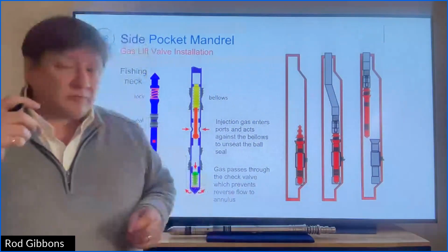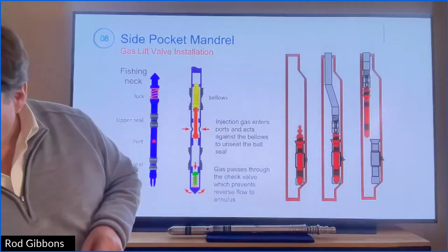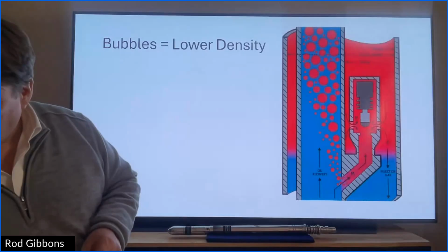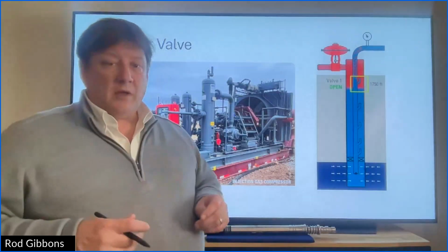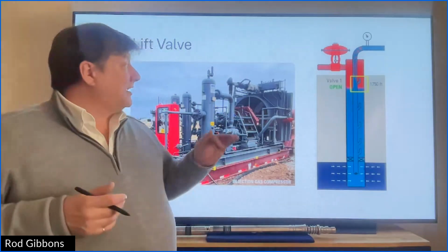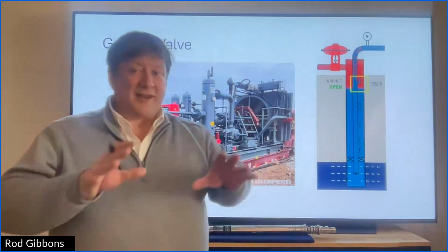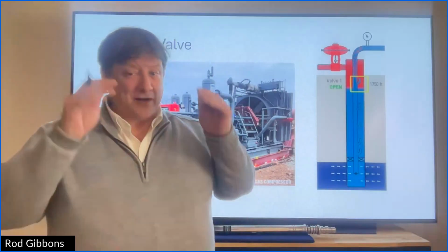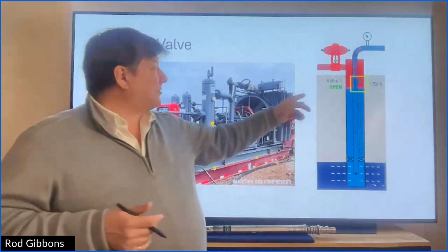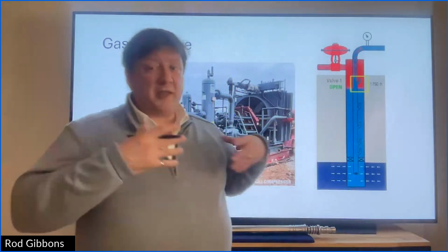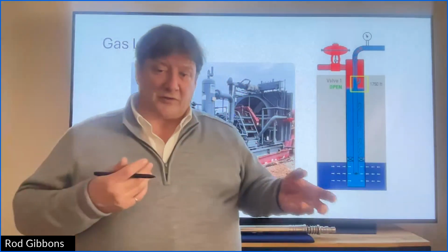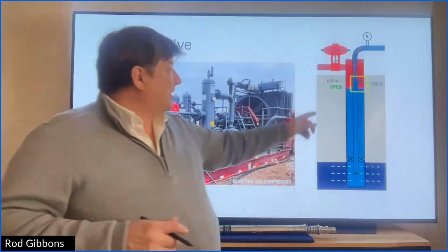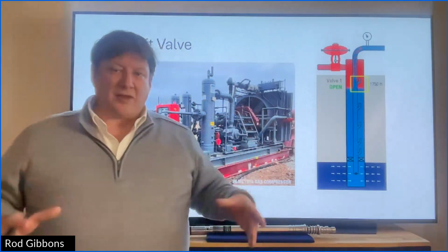So there's a question here. Is the gas in the annulus for the gas lift system pumped through a control line, or is it pumped directly into the annulus? That's a good question. I'll just go back to probably this picture. The annulus gas is actually pumped straight into the Christmas tree and straight into the annulus. You can have control lines strapped to this tubing for hydraulics or for sensors or any of that sort of stuff. But no, we are using the full annulus volume.